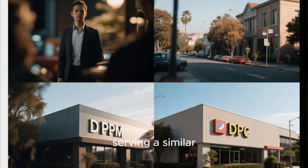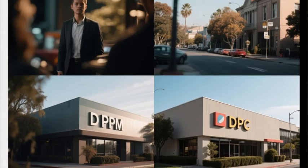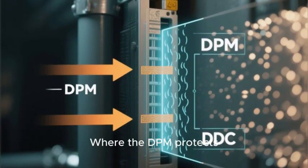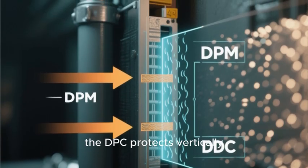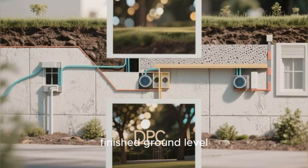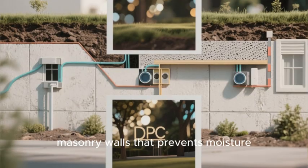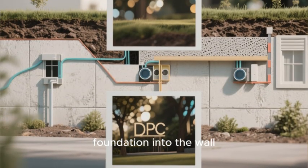The damp-proof course, while serving a similar moisture-blocking function, operates in a completely different location and context. Where the DPM protects horizontally beneath your floor, the DPC protects vertically within your walls. Installed typically 150 mm above finished ground level, the DPC creates a horizontal barrier within masonry walls that prevents moisture from rising upward from the foundation into the wall structure.